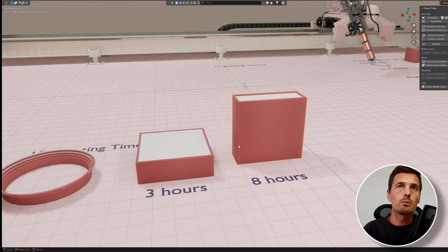If you look at this left object and the right object in volume, they are the same. But because this object you print in this orientation, it takes you around 3 hours to print. The same object sideways is going to take 8 hours to print. If you are going to design a launcher, like a big launcher, print it sideways and not in the length. Because in that way, the printing time will be reduced immensely and the price as well. So think of objects that are big, that have a big surface area, but that can be printed low. That's where the good business case is.